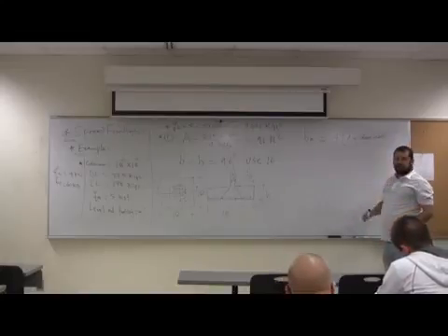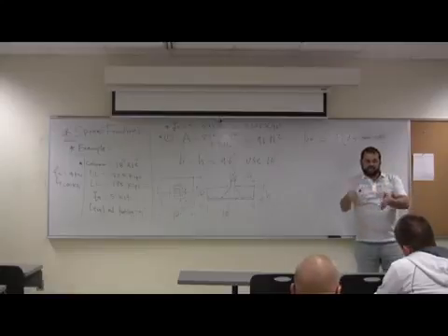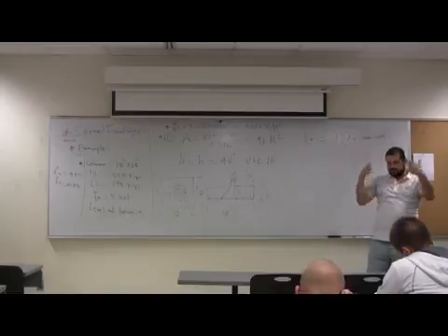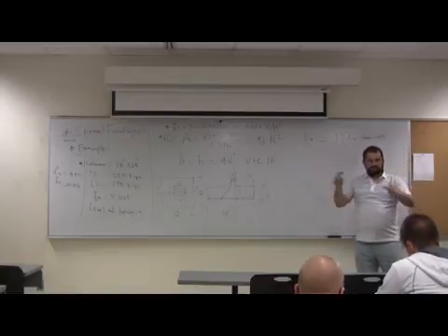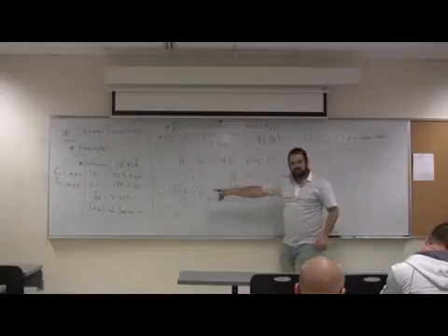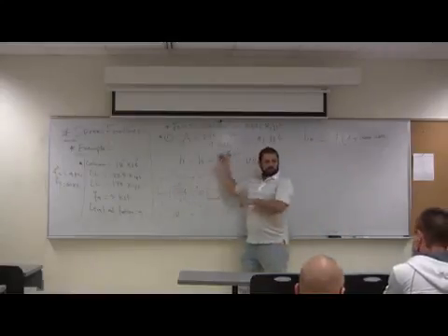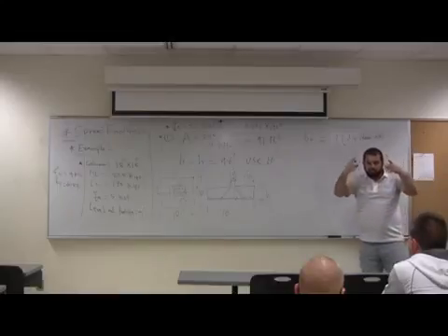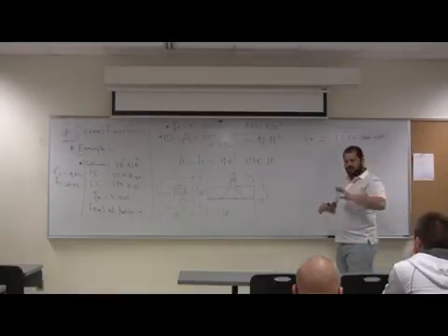If it's square. If it's not square, it will be like H plus D in one direction, 2 of them, right? Then you have B plus D, 2 of them. It's just calculating the perimeter length. This is called B naught. This is the section for punching. Let me back up now a little bit.